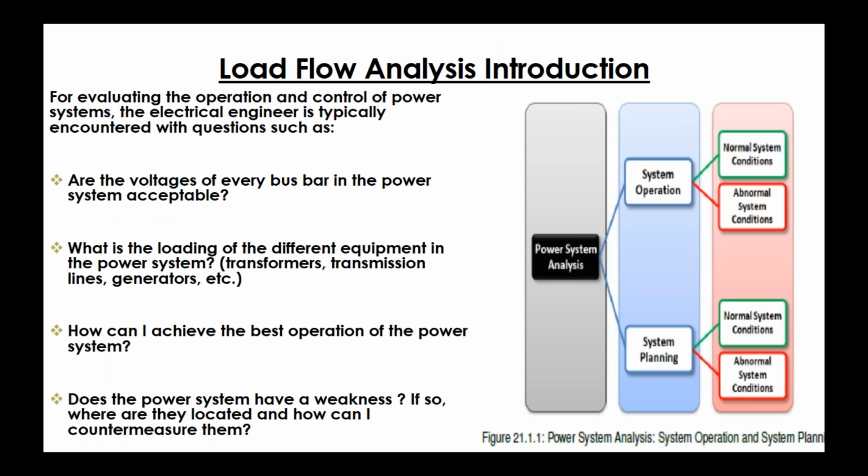Load flow analysis. A load flow calculation will determine the active and reactive power flows for all branches, and voltage magnitudes and phase for all nodes. While analyzing the behavior of an existing power system or future system, calculation is required to analyze the impact of commissioning a transmission line or a power plant. For such, two aspects are taken into account: present operation and future operation.